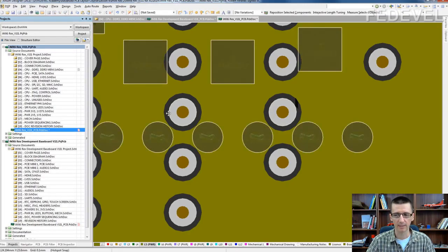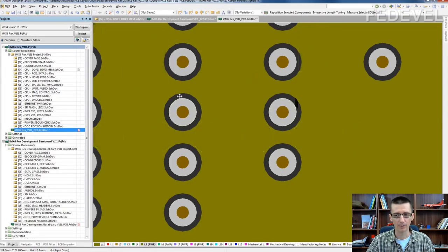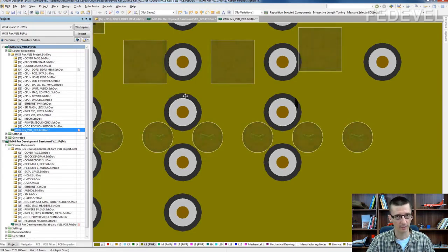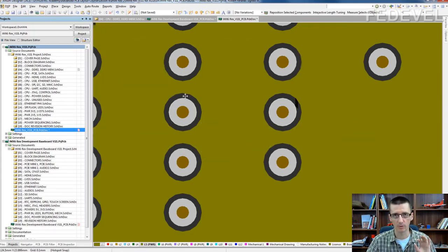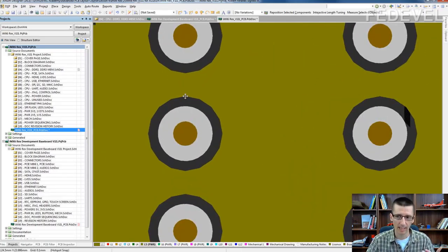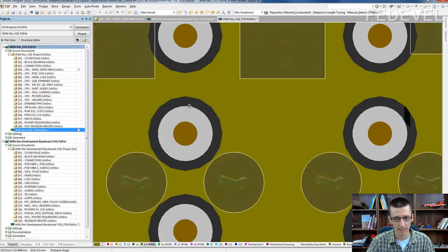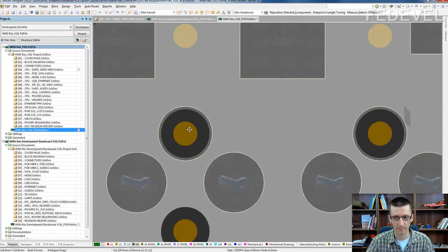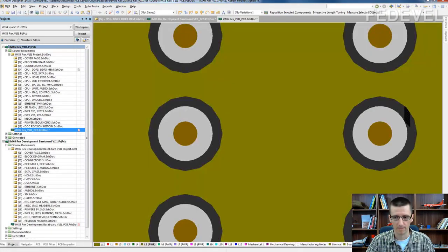They didn't like it, so I don't make this clearance smaller than the smallest clearance which is possible to be done by the PCB manufacturer. Theoretically, you should actually be able to make this hole almost exactly the same as this hole, because that's what is on this layer. Yeah. If you need to make it smaller, you can try, but check with your PCB manufacturer first.